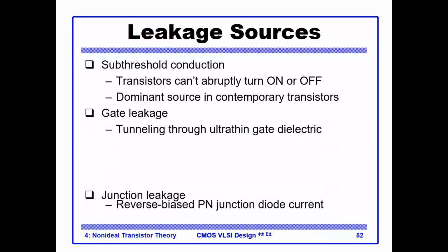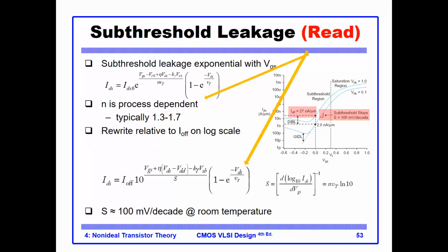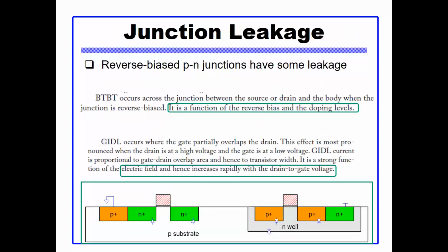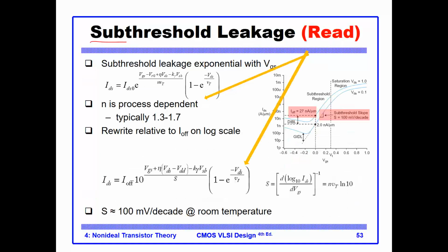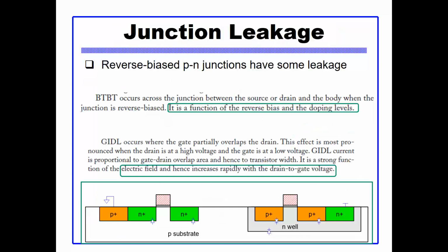Okay, so as we indicated earlier, we reiterate that there is subthreshold leakage when the device is off, gate leakage when the device is on, and junction leakage because of the reverse biased diode current. Now, there are some models that estimate the subthreshold current, and they do have estimates for the gate. These models are a bit complex, and we don't intend to cover them in this class. We'll leave them for a higher grade class, master's degree or so. So we'll leave them just as reading material.